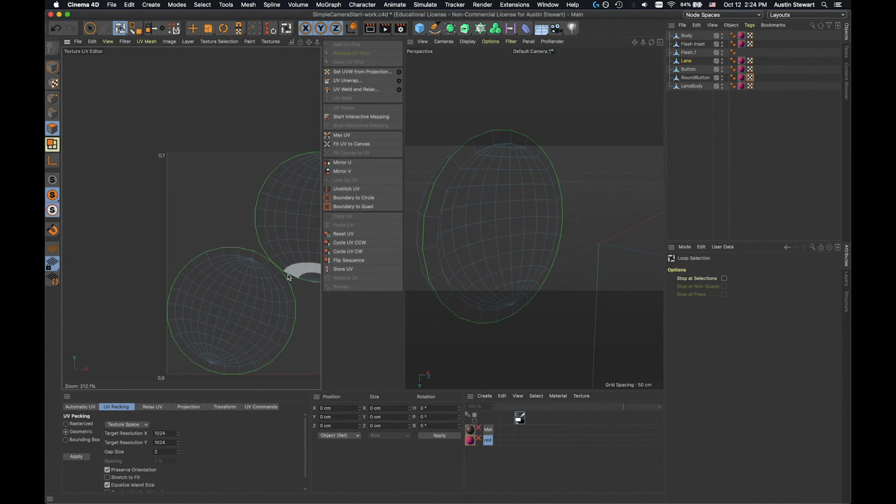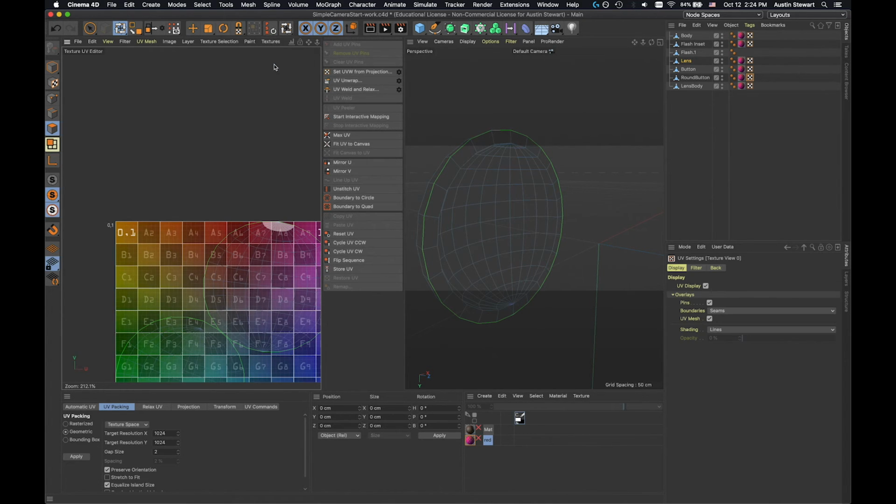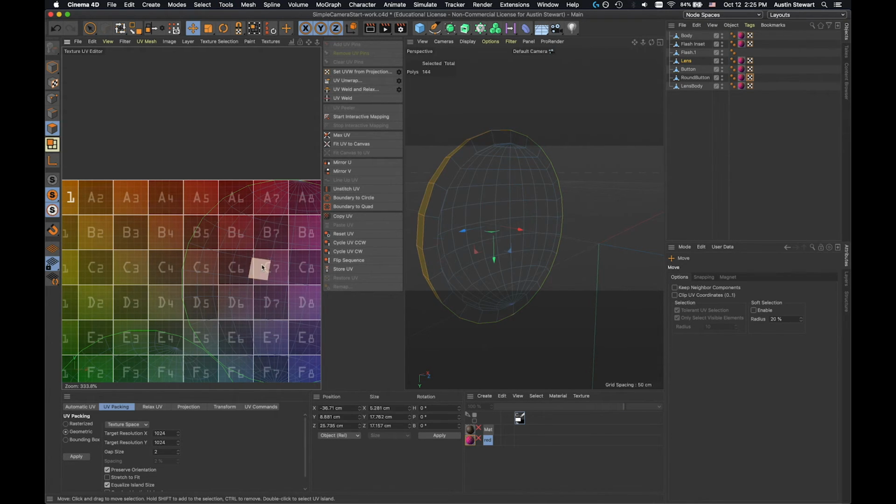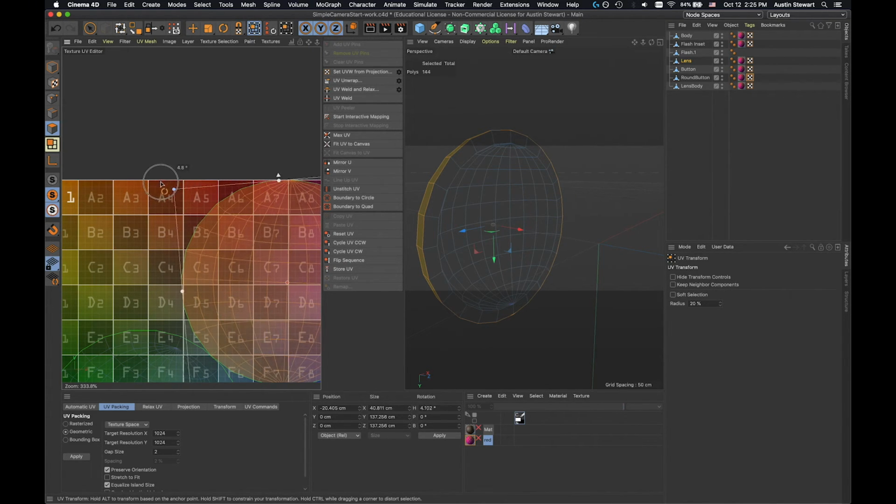And now something else, right? These are both rotated a little bit, so they're not going to be square to the grid. So I could either come here and turn my texture on and say UV map, and then select an island. I'm going to use the letter E, and then rotate this island a few degrees until that edge lines up with that grid, more or less.